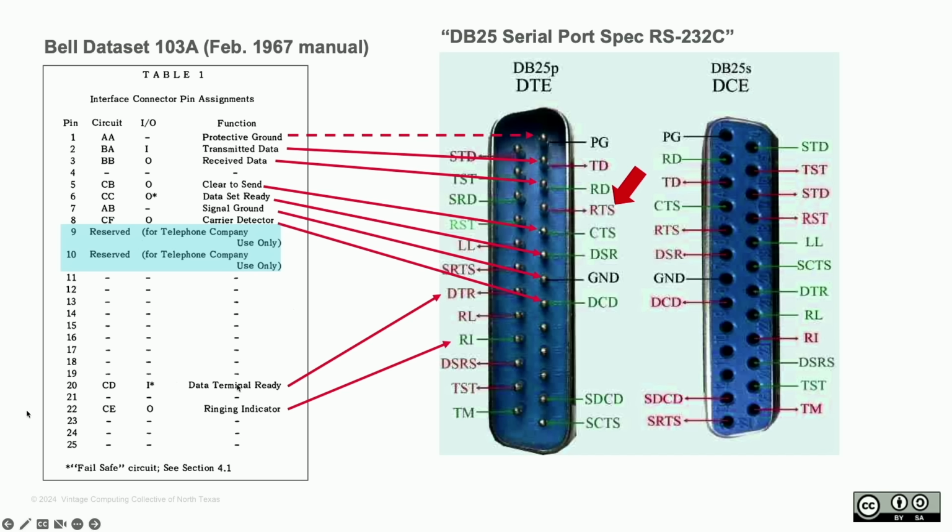So it's these pins. It's not using all these later standards. These are secondary pins. We'll talk about those in a little bit. But you're starting to get closer. You see commonality with modern interpretation of RS-232C. The big difference, they got rid of this protective ground. When I say got rid of, it's still there on the 25-pin version, but I mean on the 9-pin version. One of the pins that they dropped, the protective ground, and they added the RTS signal.